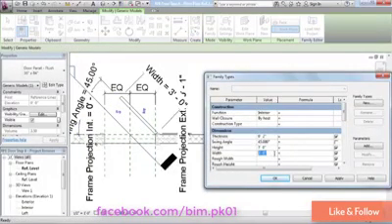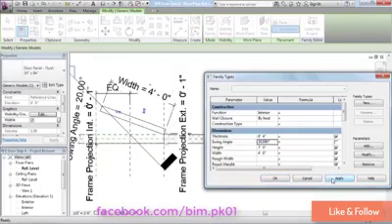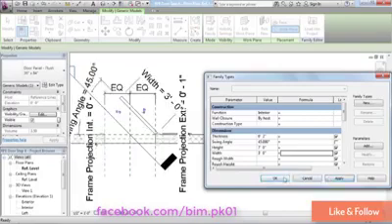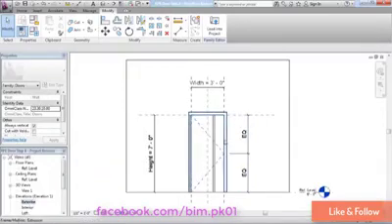I'm going to come over here. Let's try a new value for at least the two that we can see, which is width and thickness. Let's apply those. And you'll see that as the size of the opening grows, now the nested family actually grows as well. If we change the rotation, it might be even easier to see. There it is right there. And I can reset these back. Let's apply that. And let's just make sure that the height is working as well.